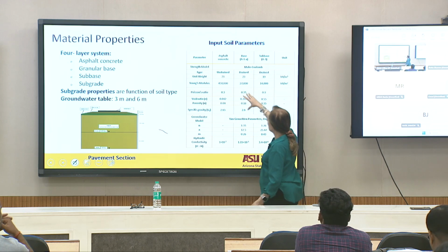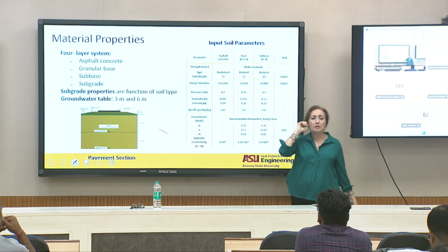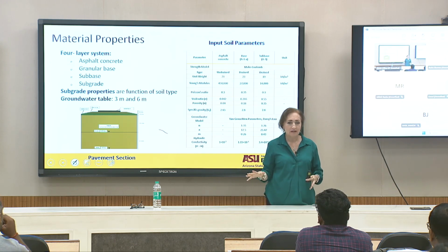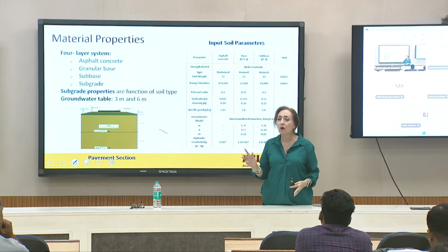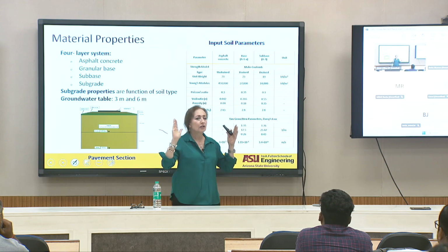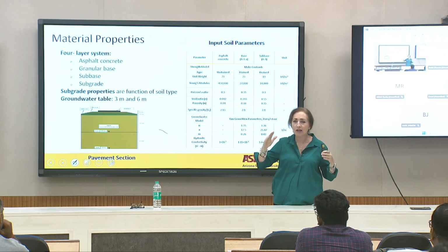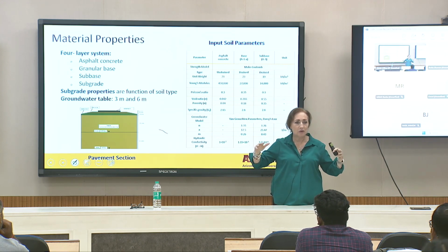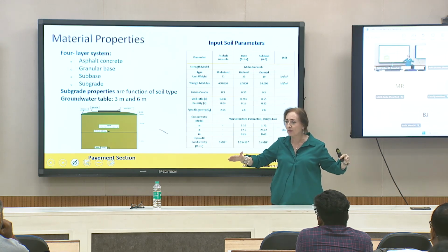So we ran also a couple analyses with the deformation analysis and the groundwater model. Why did we do that? Because we wanted to see what happened with the flooding, but we didn't want to fail the slope before knowing what happened with the flooding through different soils, right? So in this case, we put a factor of safety equal to 1.5. And it said, no matter what happens, just keep the factor of safety of this road at 1.5, okay? So we organized those conditions, we designed for that, and then the maximum condition for water will not fail the embankments for slope stability, okay?